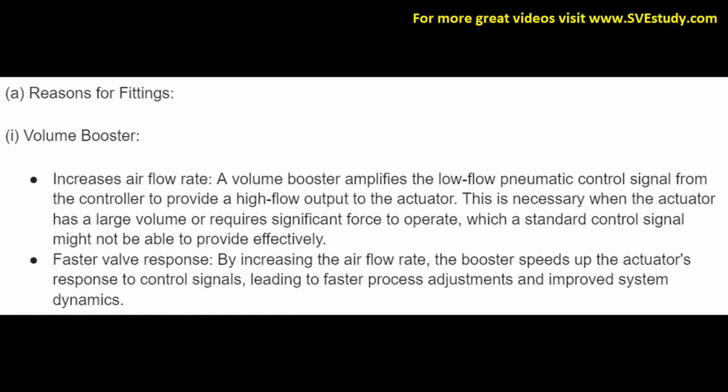Reasons for fittings. 1. Volume booster. Increases air flow rate. A volume booster amplifies the low flow pneumatic control signal from the controller to provide a high flow output to the actuator.